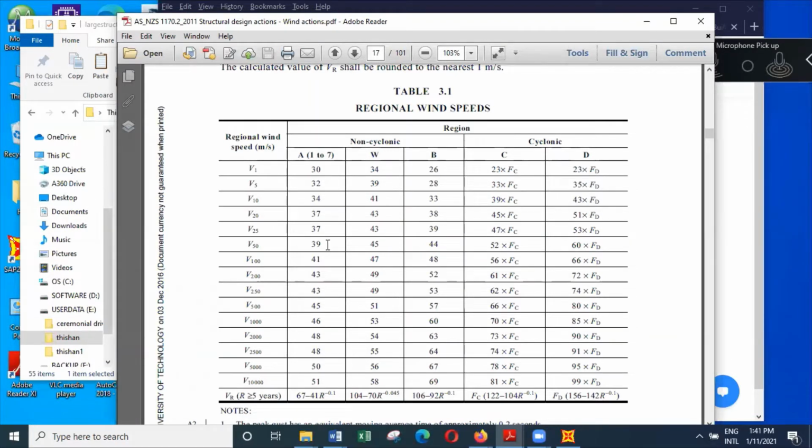So even in Eurocode, the basic wind forces are multiplied by 1.5. So we get load combinations like 1.35 dead load plus 1.5 times wind load. So the net effect is, when you use the partial factor of safety, you use the service wind and multiply it by the partial factor of safety.